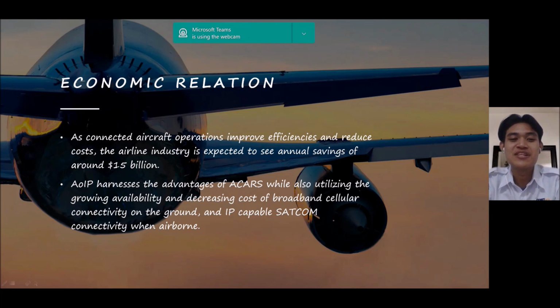At the same time, new generation aircraft generate up to 4 times the amount of ACARS data than their predecessors, leading to cost and congestion increases that reduce the overall operational gain. In response, airlines are now looking for new ways to improve throughput and reduce this cost by sending particular messages over different media. ACARS over IP, known as AOIP, is the newest option for the communication.